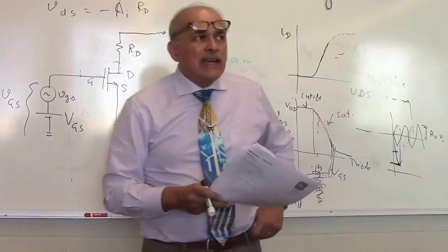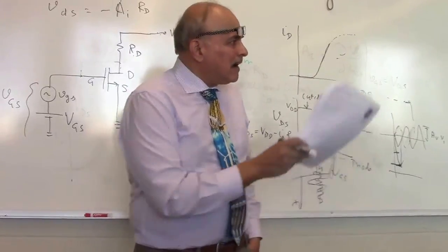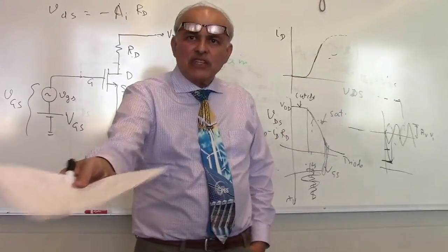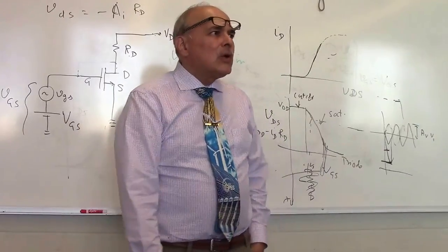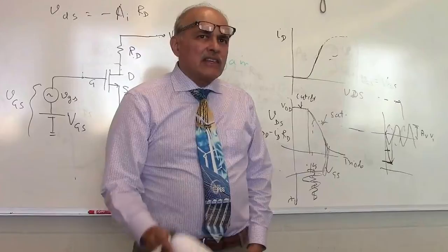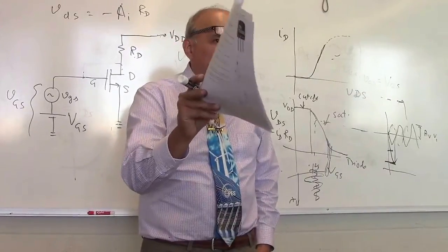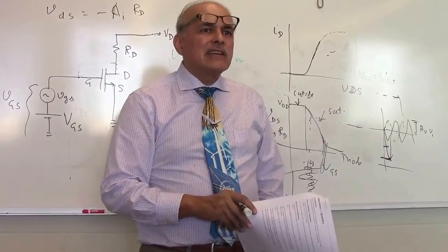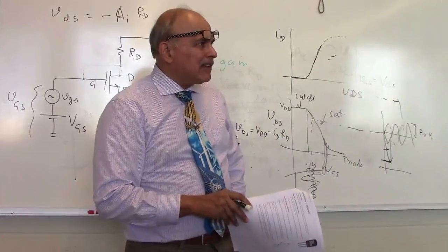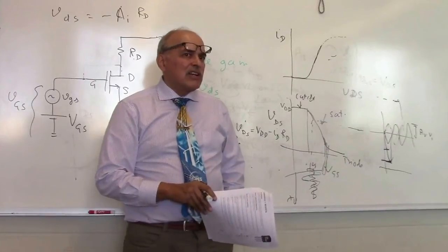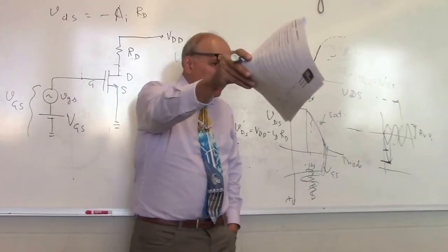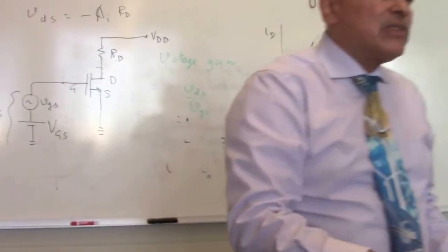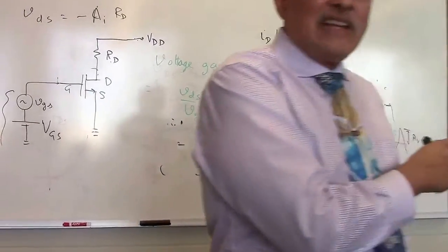Yeah, I was going to mention it. Oh, one other thing that we have to say is about safety regulations. You have the TA's names on the website. This is Shomi and this is Yichi. So really about safety, the only thing you really have to worry in this lab about safety is there are some 110 volt contacts. So don't put your fingers near the plugs. Make sure the plugs are properly inserted in the units. So you, in third year now, you should know where the power comes into your computers, your screens, or even your breadboard. So be careful about that. Now, there's a possibility that something is not grounded properly and you may get a shock when you touch something. Okay, bring that immediately to the attention of the TA.